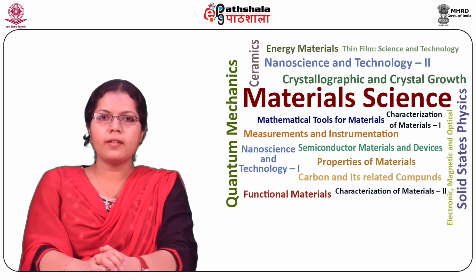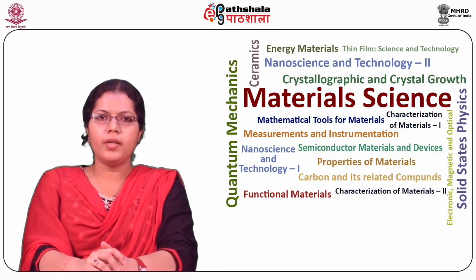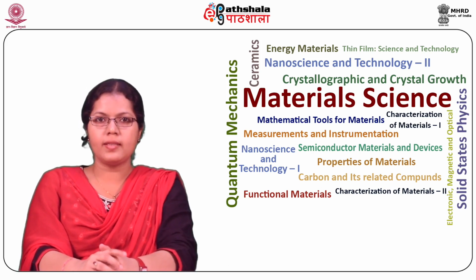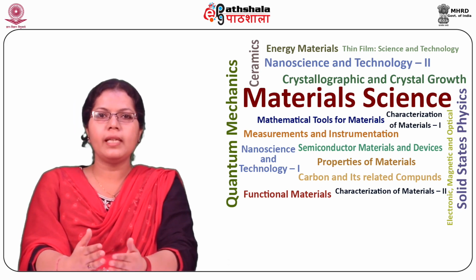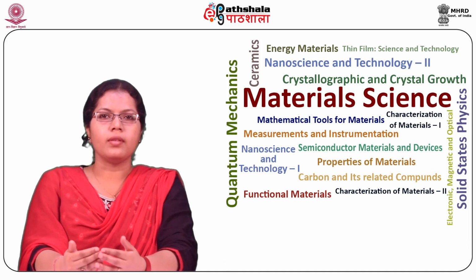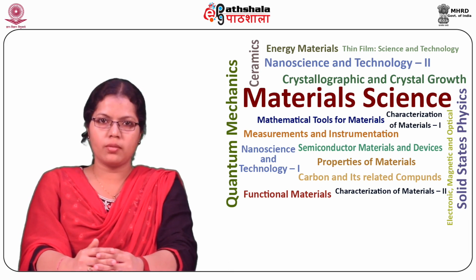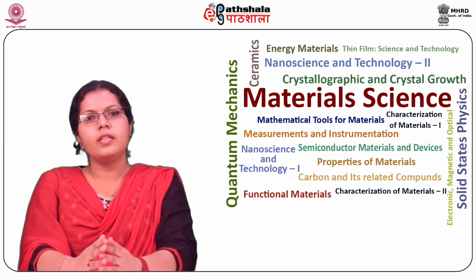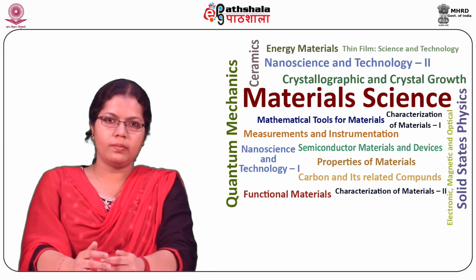First, the thermoelectric transducers. These are based on the property of thermoelectricity generation. Devices such as thermocouple, thermopile, and thermocouple gauge are based on this property for their application in the measurement of temperature, radiation pyrometry or temperature of distant objects, and low pressure respectively.